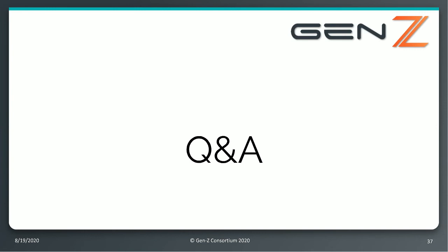I simply hooked up the Credo Bald Eagle chips and let it auto-adapt for a few hundred milliseconds and then let it fly. No doubt with some tuning of pre-emphasis or whatever on the transmit or even on the receive, we could probably get that to be even lower than it already is, which is very low.